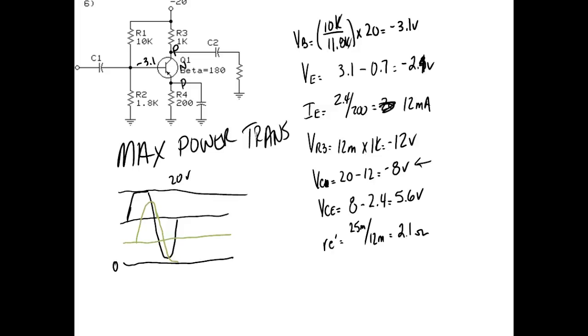Don't you remember we threw the little resistors out there and I said, okay, I got a 100 ohm source and we're going to do 1K, 110, and we got the maximum power transfer. If you had a 100 ohm source and you had a 100 ohm load, you got the maximum power to the load, right? And that's what we're trying to do. We're trying to get the maximum power transfer. When you get maximum power transfer in a communication channel, when the watts match, when the impedance in the channel matches. So that's important. I don't want a low impedance amplifier to feed a high impedance load. I want a low impedance amplifier to feed a low impedance load, right?